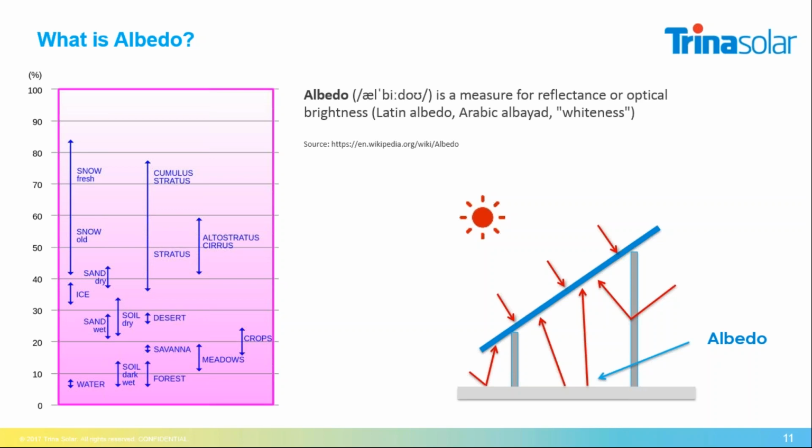So what is important to know for the system design and to calculate the benefit of a bifacial module is that you also need to know the underground properties of the location. That means you need knowledge about the location to make a proper system design, and to avoid, for example, that with quite good reflectivity that you don't consider in the inverter sizing, you cut off the additional power because the inverter runs into limitation. This needs to be avoided to get the most benefit out of the bifacial modules.